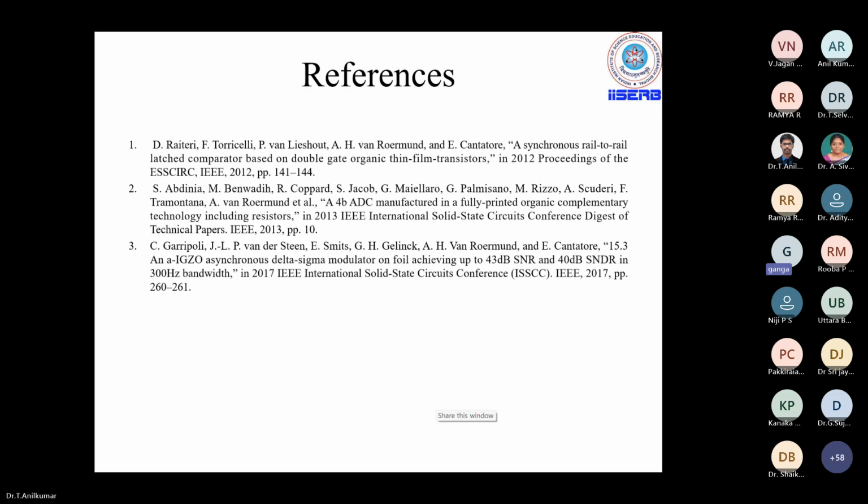So with this, I would like to conclude my presentation. Here we have seen ring oscillators with CMOS technologies, the low power ring oscillators with skew technique, current starving technique, and a combination of these two techniques in 65 nanometer technology implementation. Then we also have seen the ring oscillators with oxide TFTs on flexible substrates. Here we have seen a lot of designs, like the conventional designs, novel designs, and so on, and their experimental characterization.